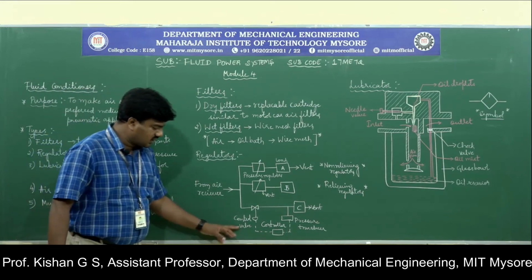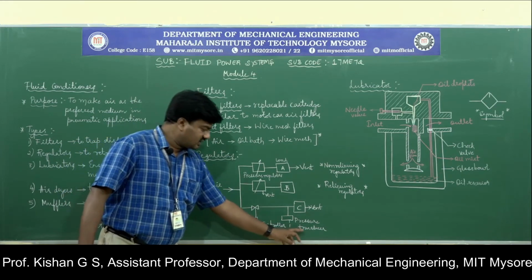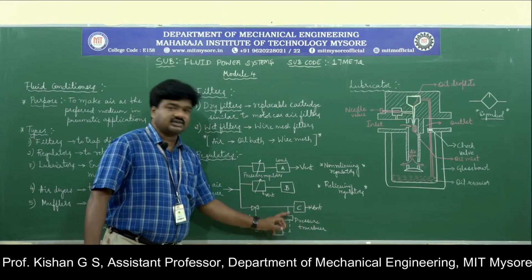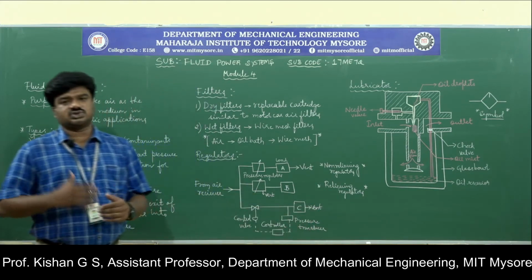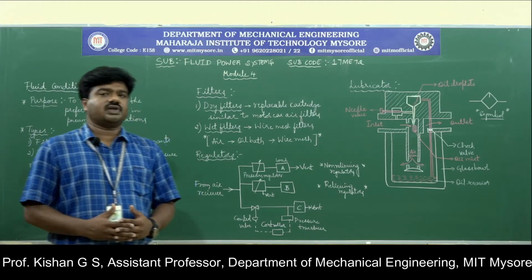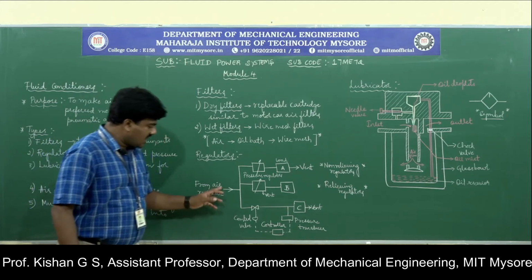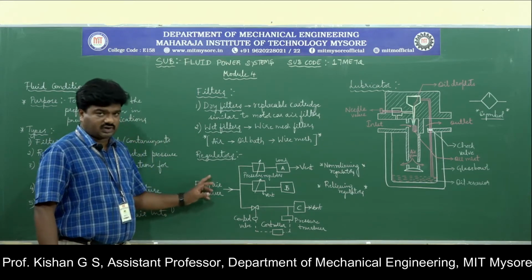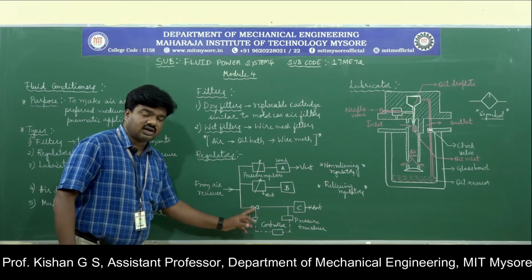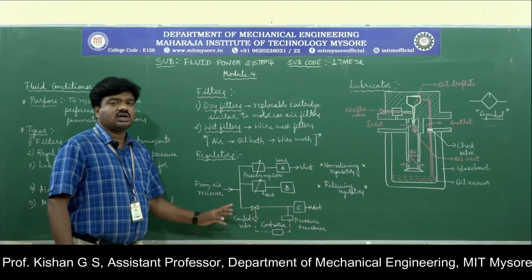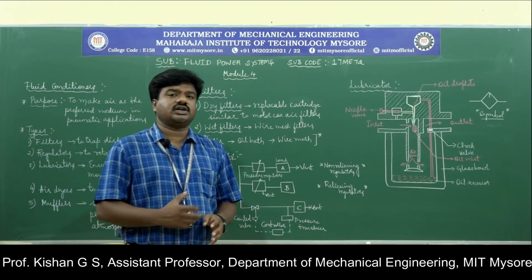Here you can observe there is a control valve, an electrical controller, and a pressure transducer, and this is work C being defined, and there is a vent to let the pressurized gas go out of the system, that is, to the atmosphere. The air taken from the receiver is made to pass through the control valve, which controls the flow rate as well as the pressure at which the air is taken into the system.